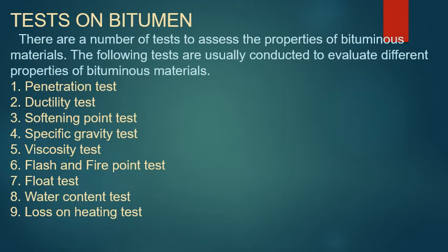Means whatever bitumen we are going to use for the construction, it should sustain the maximum load, axle load, and the temperature variations. At night time the temperature may be low, and daytime the temperature may be high. Generally we take the maximum temperature with respect to Indian condition, that is during the summer we observe maximum temperature. So which one to take? There is a question. Generally it is recommended to take the 7 days maximum temperature for the design.